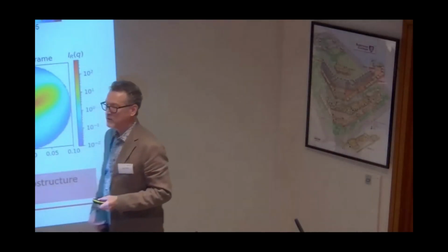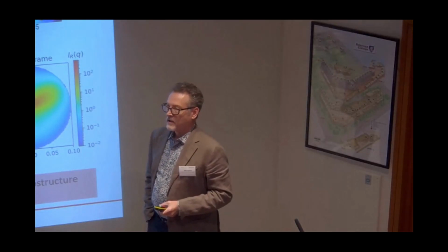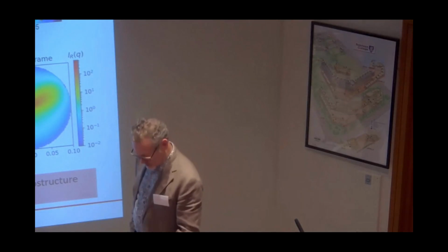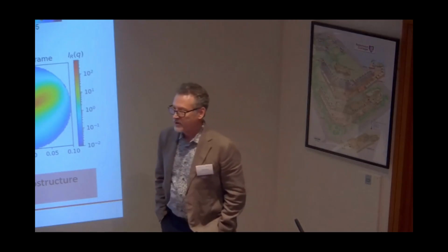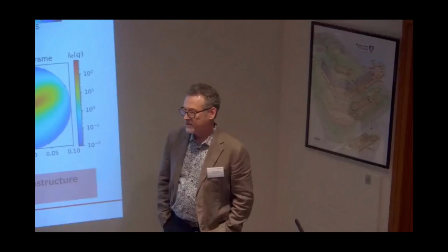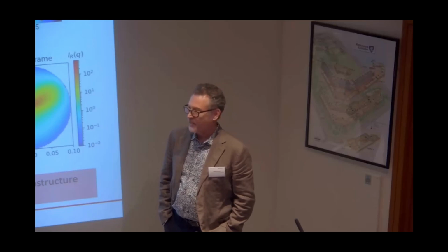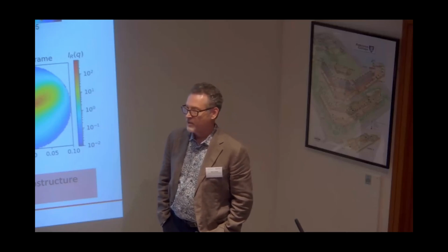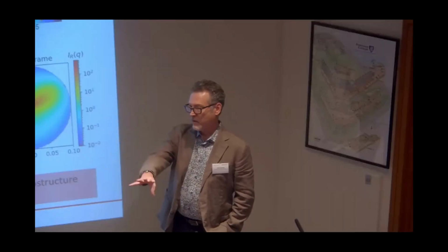Can you say a few words on how one determines the stress? The stress is under the divergence operator. We have the divergence-free part of the force density, and the stress is under the divergence operator. The problem is that the divergence operator has a non-trivial null space, so you can't uniquely determine the stress from the force density.